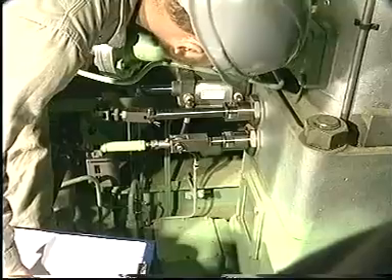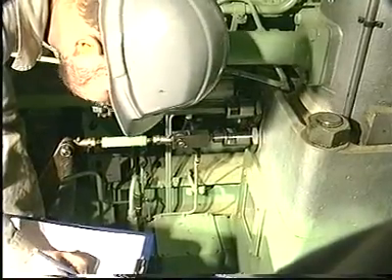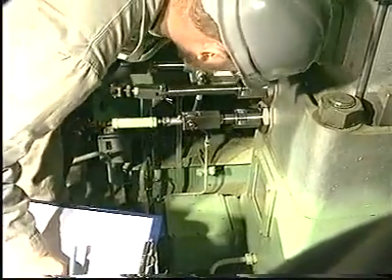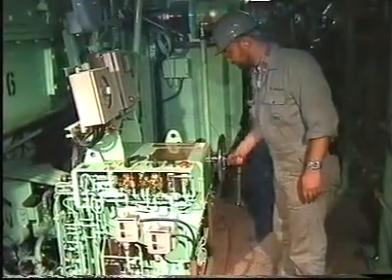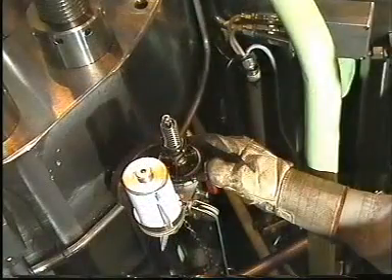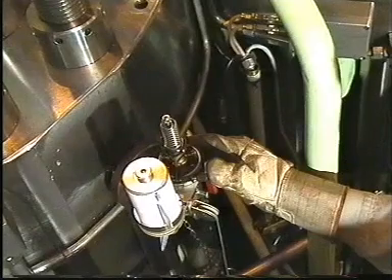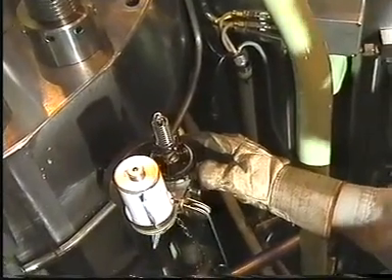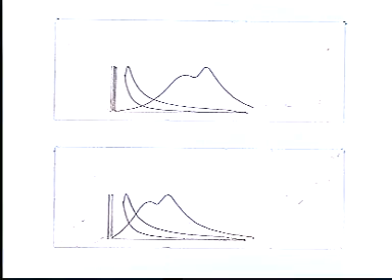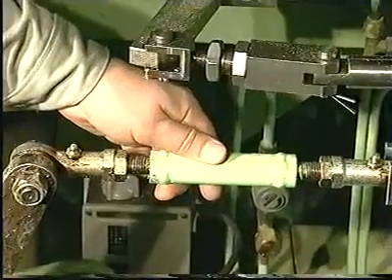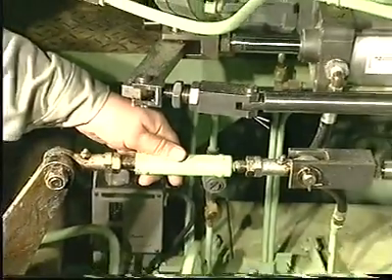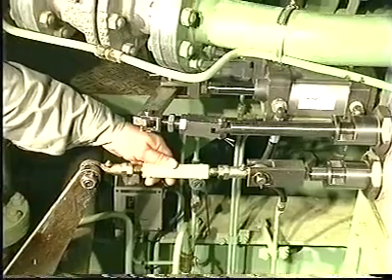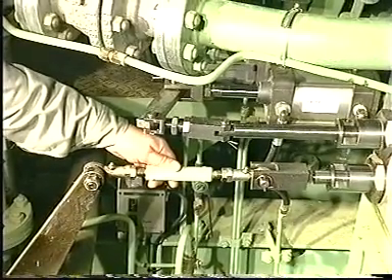Note down the fuel pump indexes and VIT indexes. Run the engine up until it corresponds to 100% MCR. Use the indicator drive or PMI system to adjust the load so that it corresponds to 100% MCR. The mean indicated pressures of the individual cylinders must not deviate more than 0.5 bar. If the deviation is more than 0.5 bar, adjust the load distribution on the fuel index rack of the individual cylinders.